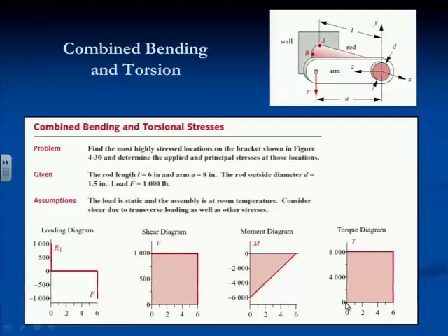And then the twist: the torque at the end of the beam is resisted by a torque in the wall, and that puts a torsional stress, which is shear, which is not uniform but increases with the radius, all the way around the circle, right?